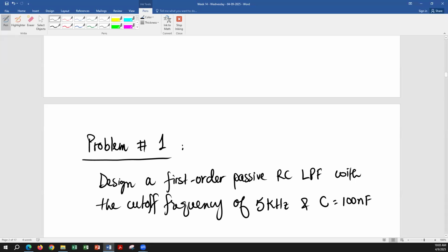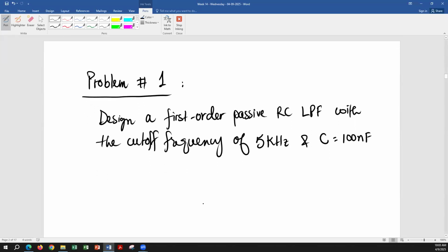Now, some values might not be very wise to use in a design. And what are those values? Very low values of resistor or very high values of resistor, right? Those are not very good values to use because very low values are susceptible to low level noise, which I forgot, it's called pink noise or something. And likewise, very high values are also susceptible to noise.